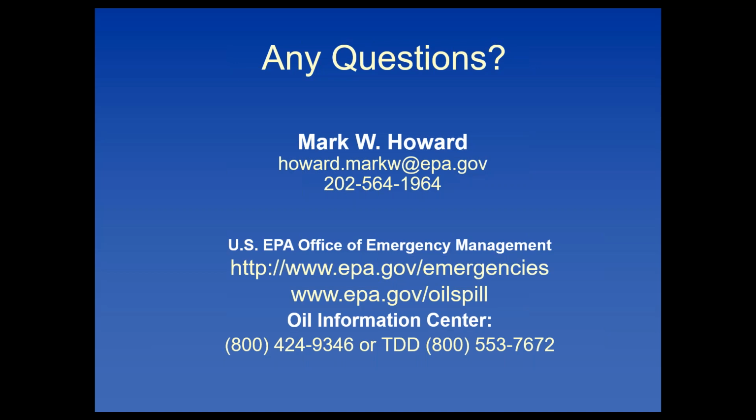It gets a little bit more complicated with USTs. So again, if you have both USTs and ASTs, we don't regulate USTs, but at an otherwise regulated SPCC facility, so you break the threshold on aboveground and you have some underground tanks, even though we don't regulate the underground tanks, if it's an SPCC facility, the transfers from the dispensers are actually subject to the SPCC rule because the dispensers are not part of the UST system.